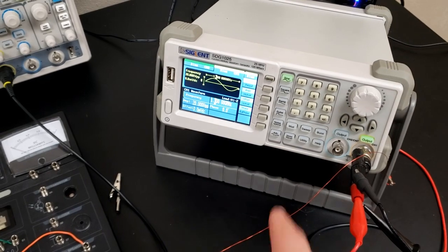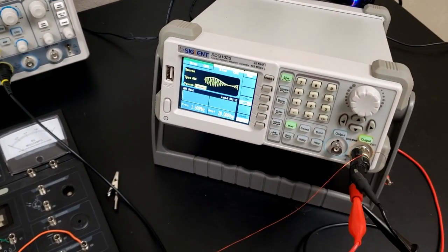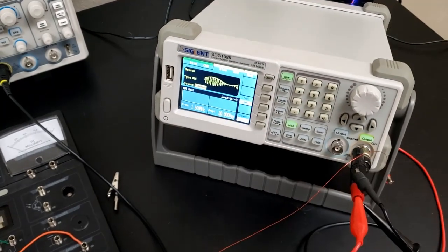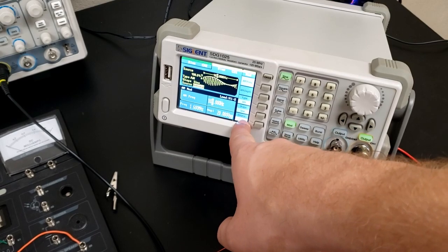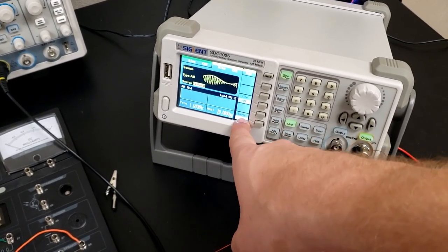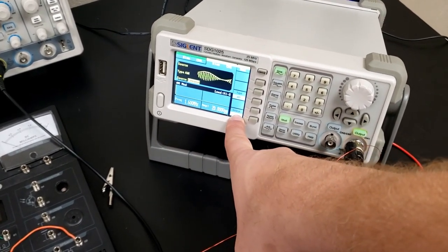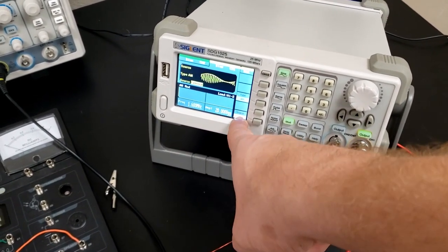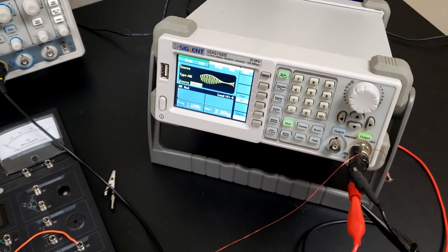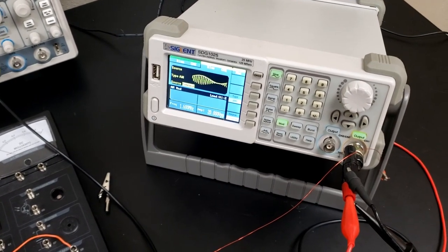So what we'll do now is we'll go ahead and use this modulate function that's included in our function generator. And there's an option down here. It might be hard for you to see, but if I click that, I can change it from an internal source. And if I click it again, I can change it to an external source. So this means that I can plug my phone or my laptop or whatever I want into the back of this machine, and then the carrier signal that we have set up at the 1.6 megahertz will be modulated by the signal coming from my phone or whatever device.